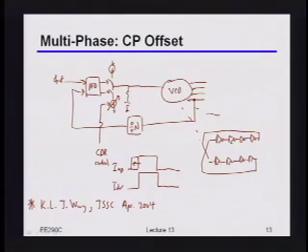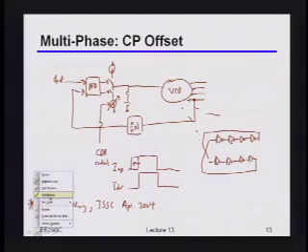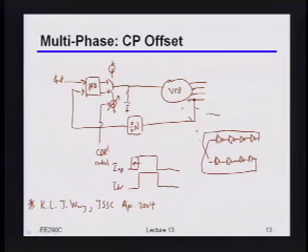Okay? So basically, it's still allowing you to do a dual loop CDR, because the bandwidth of the CDR itself is still going to be set by the accumulators and everything that you put before this. It's just that you're going to be hacking the characteristics of the PLL in order to get that phase offset on multiple phases all at the same time. Is this clear to people?